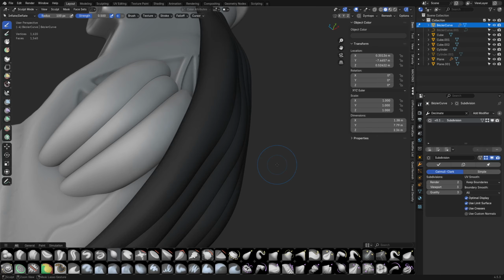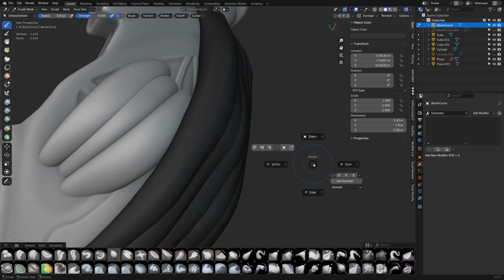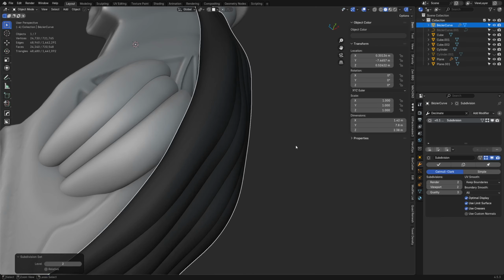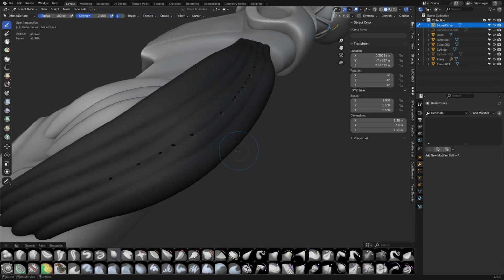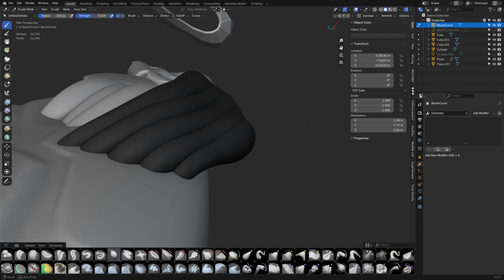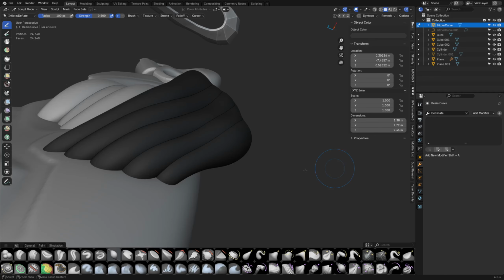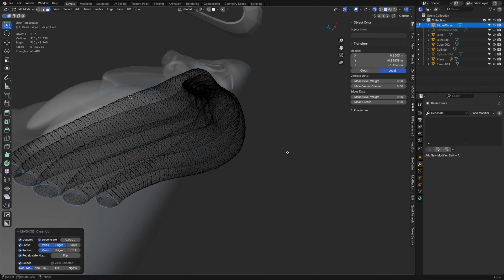Okay. Probably should Control Z that, get rid of that, and try this again real quick. Or excuse me, subdivide it and apply it. Then remesh it. Okay, and see if that works out. You can see it actually developed some holes, which I didn't realize it was going to do. I wonder if I just increase the resolution, if it becomes better. No. We got holes in here somewhere on the ends.